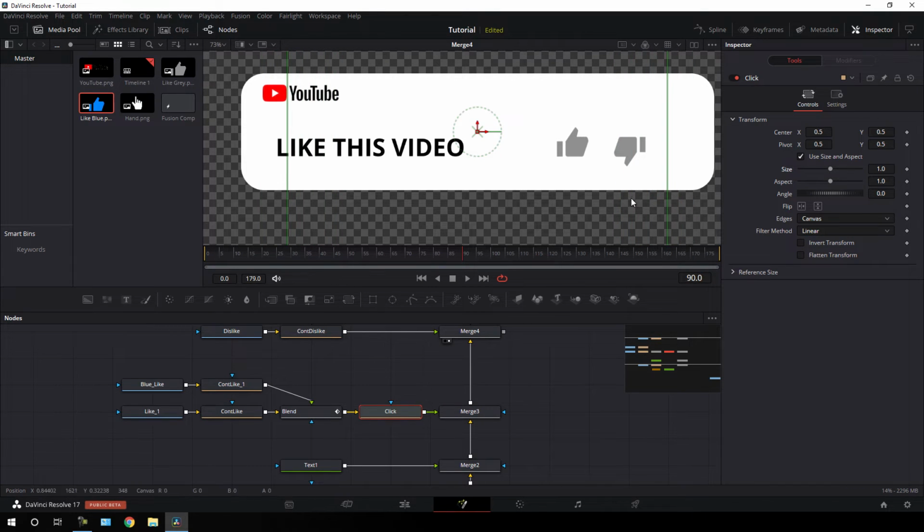But as you can see, there is a problem over here. So what we have to do, hit Ctrl Z to go back, and we have to set this pivot point in the center of this like button. So what we have to do, just select this click, and here we have this pivot. So hold left mouse button on this X position value and just drag it like this. Drag this Y value as well.